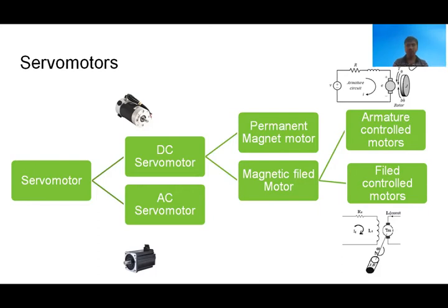So servo motors are used in automatic control systems. The system is known as servo mechanism when it is used to control the position of an object. The main purpose of the servo motors is to convert an electrical signal applied to the motor to an angular displacement of the shaft. The operation of servo motor is either in a continuous or step motion, which depends on the construction. A variety of servo motors are available for control system applications.